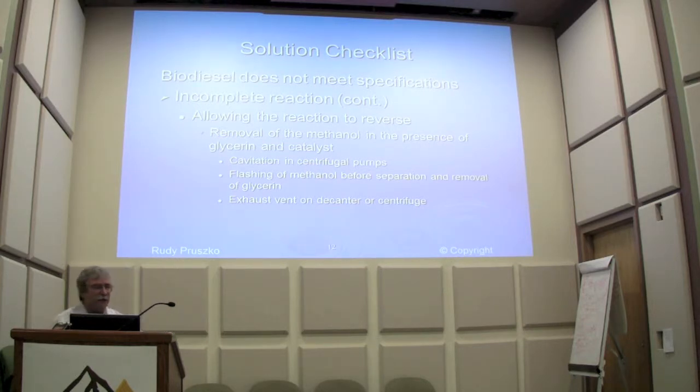Now, one of the places, if you're using centrifugal pumps and you're running bare minimum excess methanol, and you're running the mixture out of your reactor and going back in the pump, and you get a little bit of cavitation in the pump, that will pull the methanol off, and then you have high shear methanol that's sort of cavitating in the pump.